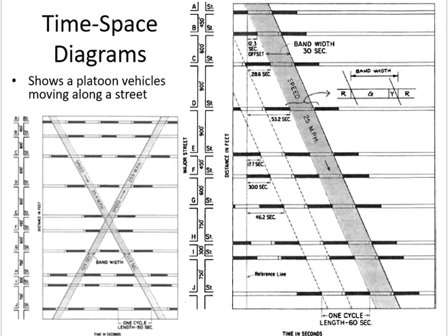The progression starts when the green starts. The first vehicle leaves the first intersection. This is the start of the progression. Any vehicle which comes after that will have green, so they will keep on moving. When is the last time a vehicle can come and still be able to move? That is the yellow. Clear? So from here to here, this is what we call bandwidth.